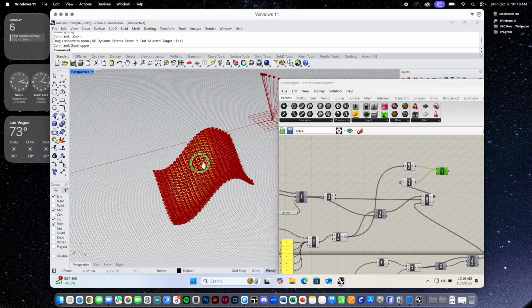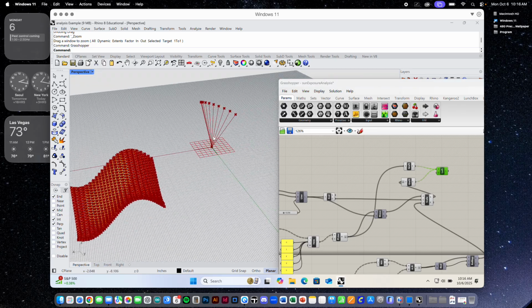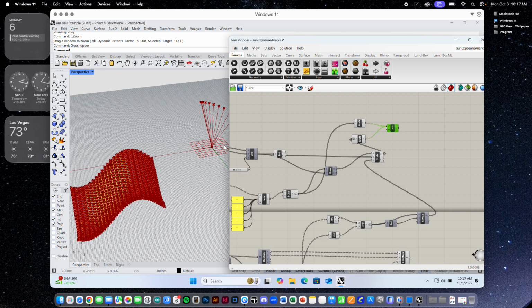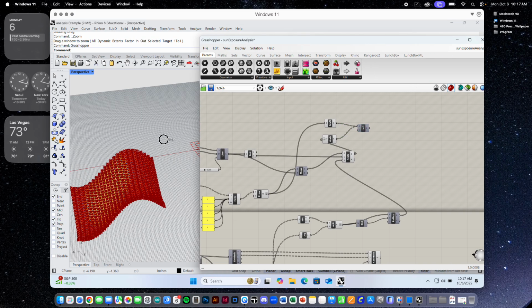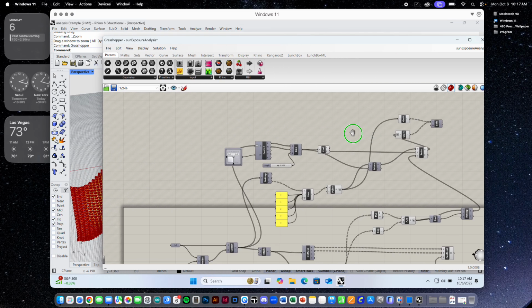And you can see that what I'm doing is I've defined a set of sun rays, and there's like 8 or 10 of them here, I don't know, whatever. So in other words, acknowledging that the sun's in a different location throughout, let's say, part of the afternoon. And this isn't necessarily me saying here's the latitude, and here's the dates, and here's the times. It's just me demonstrating this. I just made some layers. Okay? What I can do is I can use, in Grasshopper, bring those rays in. Those basically are just vectors, a direction and a magnitude.